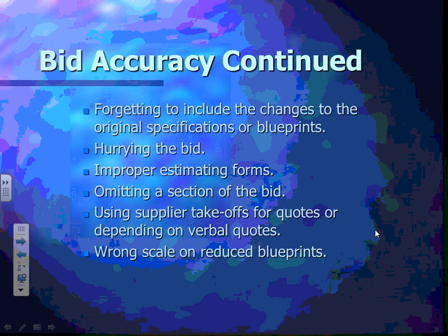Forgetting to include changes to the original specification, if any, or blueprints. Hurrying the bid just to get it in. Improper estimating forms. Most important things, guys. Omitting a section of the bid, supplier's takeoff for quotation, or depending on verbal quotations, what not.